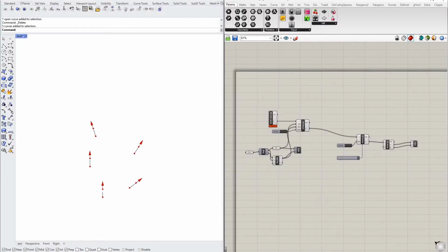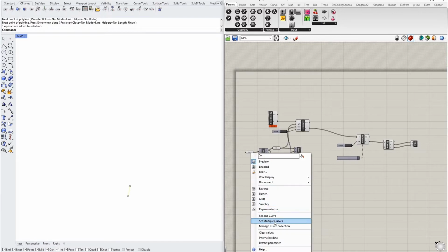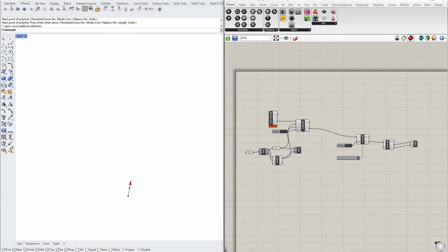We will start with one Boid instance to keep it simple, so we can see what is happening as we define the logic, as we prototype this specific behavior. To do this, we will make one line geometry and reference it in the inputs for the Boid system. Now let's create 2 curves in Rhino, and create a reference to them in Grasshopper.